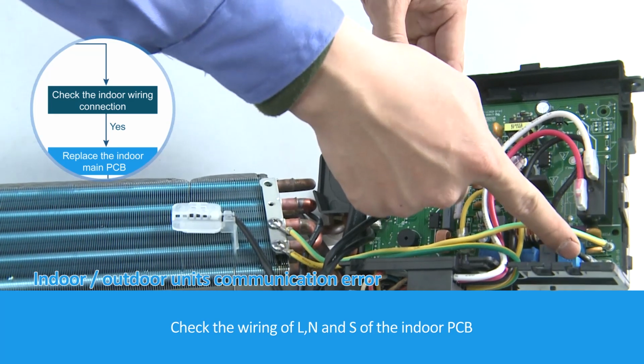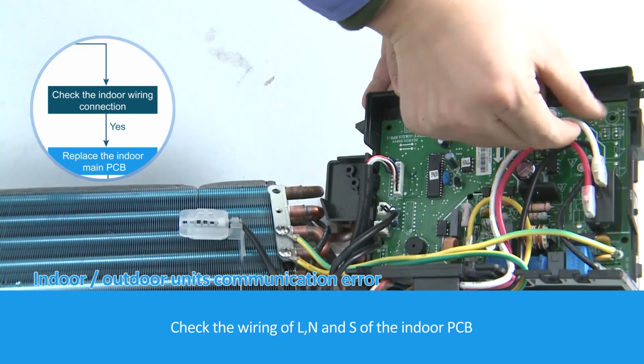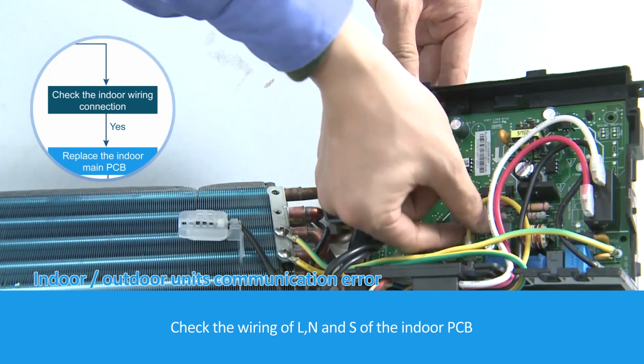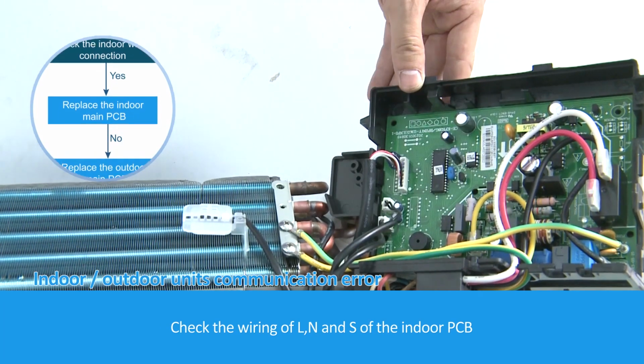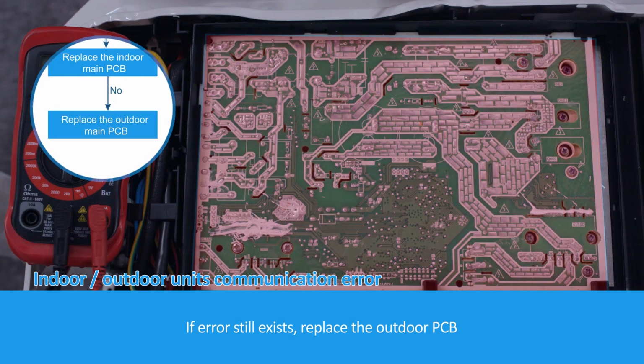Check the wiring of L, N and S of the indoor PCB. If error still exists after the maintenance above, replace the indoor PCB. If error still exists, replace the outdoor PCB.